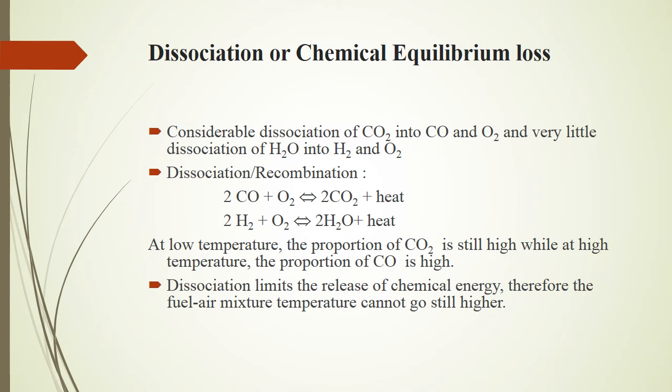So we can say the general effect of dissociation is a suppression of a part of the heat during the combustion period and the liberation of it as the expansion proceeds, a condition which is really identical with the effects produced by the change in specific heat. However, the effect of dissociation is much smaller than that of change of specific heat.